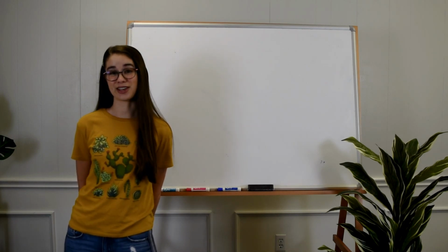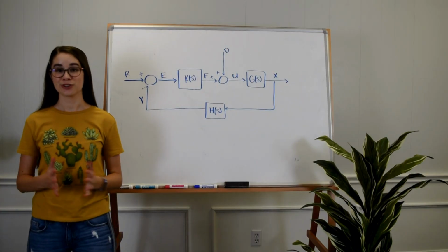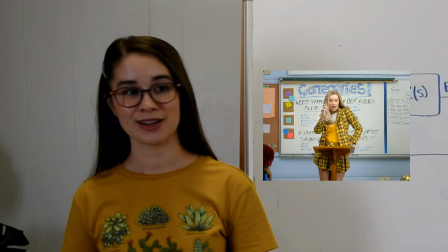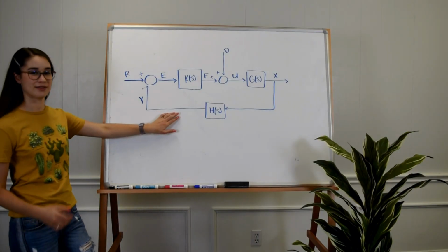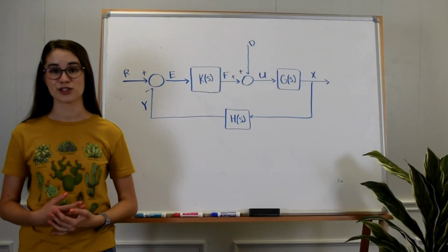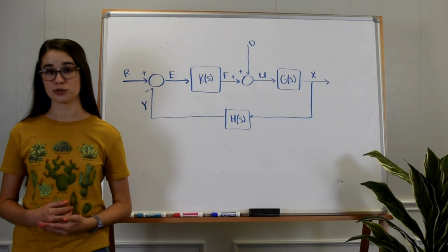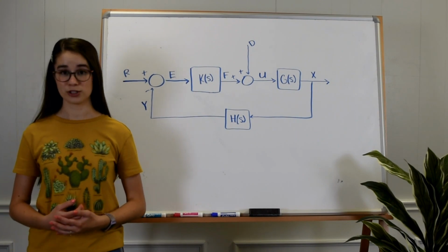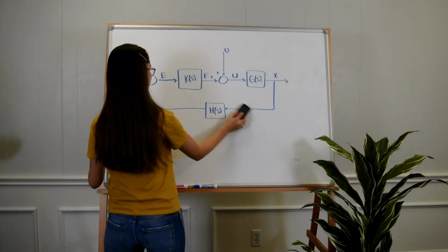Today, we're going to be talking about block diagram algebra. So first things first, we need to understand what each piece of this pretty little picture means. Now, there are three basic shapes: circles, squares, and lines. Circles denote addition or subtraction, squares represent multiplications, and lines represent variables. Let's take a look.